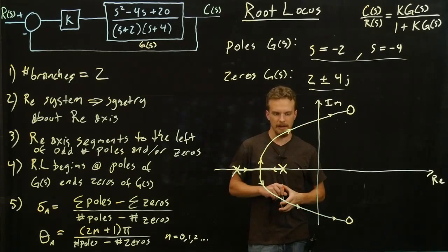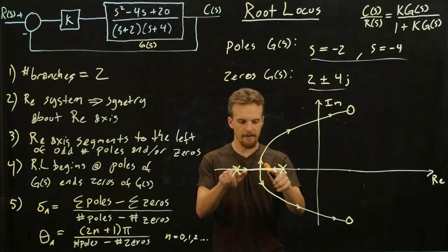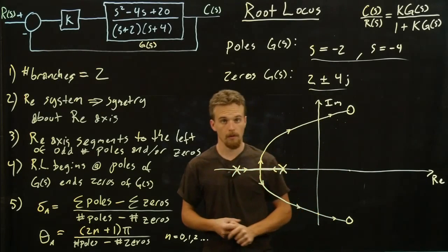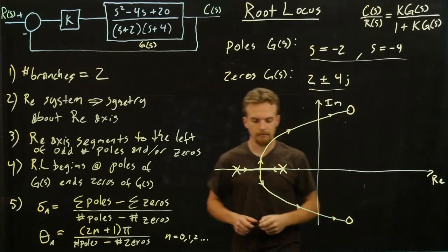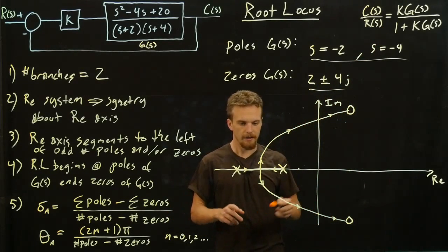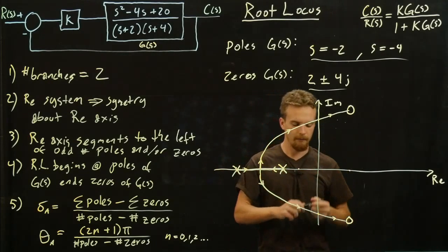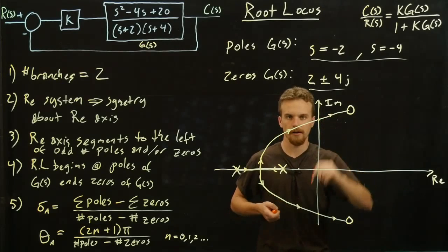Because let's keep in mind what this is actually plotting. These values, little points on this line, are the poles of this closed loop system as we vary k. So if we keep increasing k, we get to this point, we break away, and we increase k so that we get to this axis and just barely cross it.